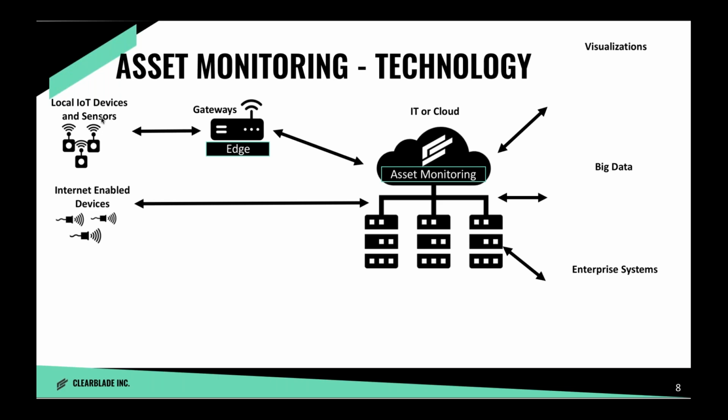In order to do that, you need what's called edge processing that runs on a gateway. That allows you to get locally and physically near those devices, plug directly into them, get on the local network to pull that data in, and that's where the edge portion of the asset monitor runs. What's great about this is because of this design, you actually can take those rules, that level check rule, and do that level check rule all the way down out in the field.